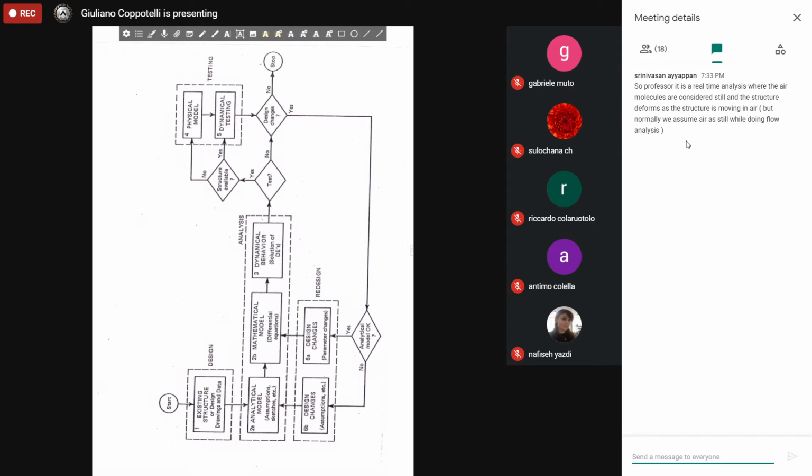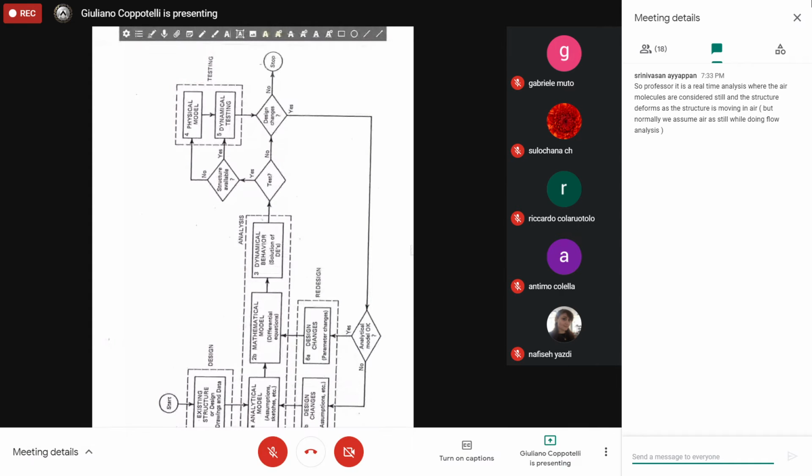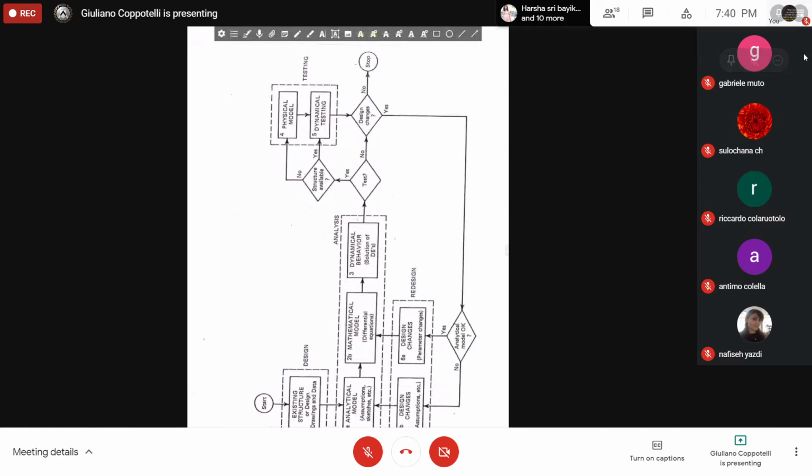For your information, when you are doing what we call the ground vibration test, that is, your experimental modal analysis for whatever vehicle, the effect of the air surrounding the structure is visible. On the contrary, when you have the flight test, it is very important to take into account the airflow, and actually we have a whole aeroelastic effect to consider. For that case we are very interested in the overall couplings between the structure elasticity, the structure inertia, and the aerodynamic flow around the structure.